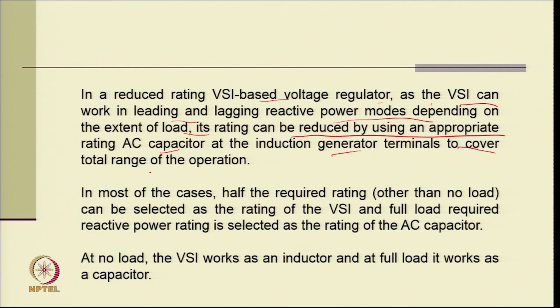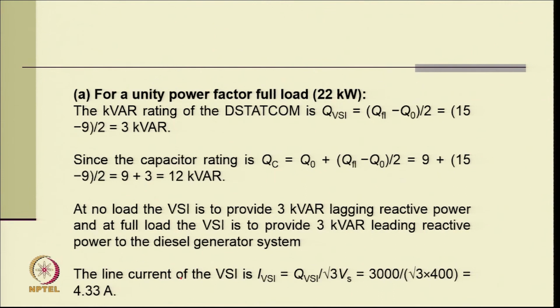So, an induction generator is available to cover the load range. In most of the cases, half the required rating other than no load can be selected based on the rating of the VSI, and full load reactive power rating is selected as per the rating of the AC capacitor. So, at no load the VSI works as an inductor, and at full load it works as a capacitor. So, for unity power factor load of 22 kilowatt, the kVAR rating of this STATCOM is (QFL minus Q0) by 2, so it is (15 minus 9) by 2, 3 kVAR. So, the capacitor rating is now Q0 plus (QFL minus Q0) by 2. So, it comes like 9 plus 3, 12 kVAR.